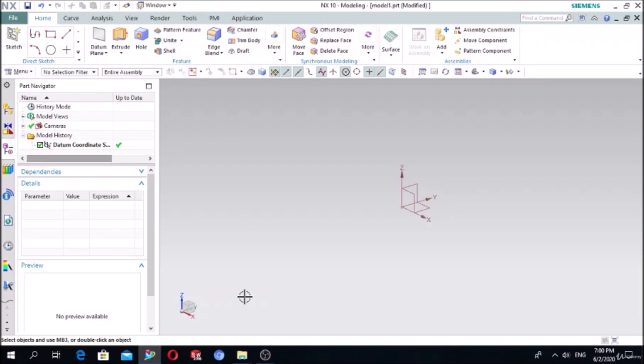As you create a sketch in NX, some dimensions are added to the sketch elements. These dimensions are called driven dimensions, and they do not have any control over the sketch geometry. If you want these dimensions to control the shape and size of the sketch geometry, you have to convert them into driving dimensions. Driving dimensions are so named because they drive the geometry of the sketch. You can add driving dimensions to a sketch by using the rapid dimension command.